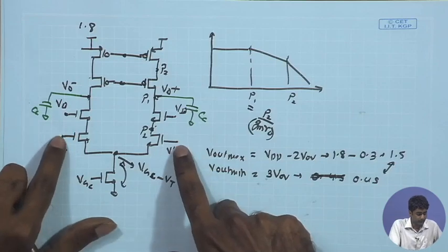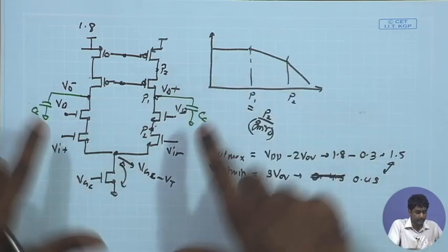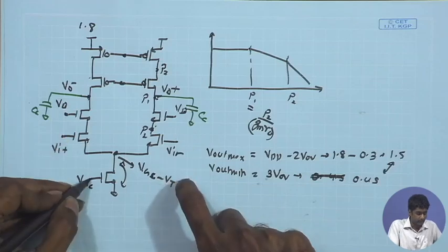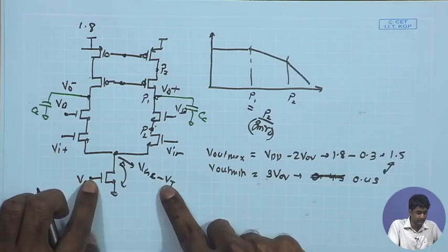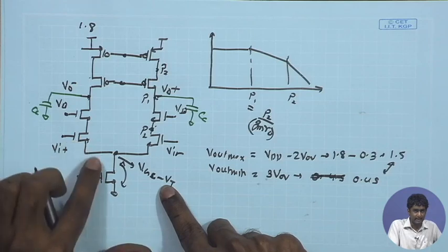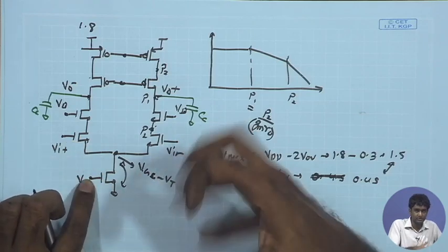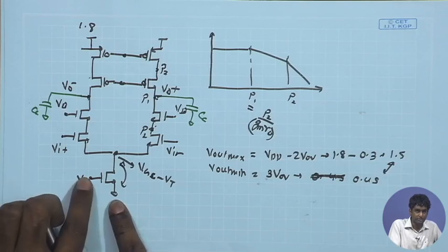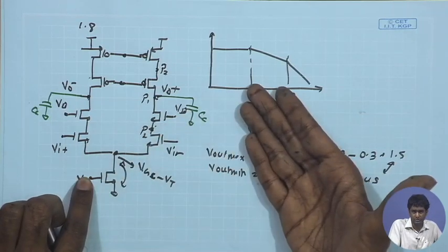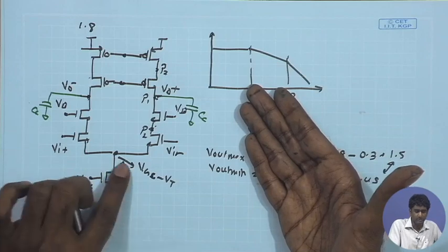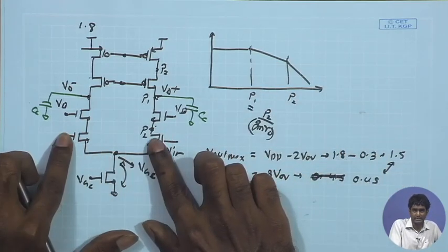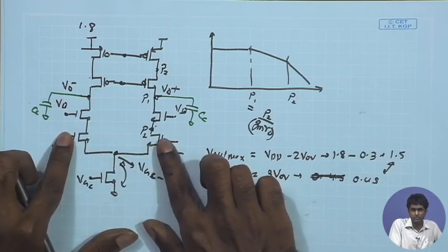So if I look at my minimum allowed DC potential that I arrived at, that was Vg minus Vt plus Vgs, and Vg minus Vt, once again because it is low current biasing, can be close to 0, maybe 0.1 volt, and then you have Vgs, which is again close to Vt, around 0.5 volt.